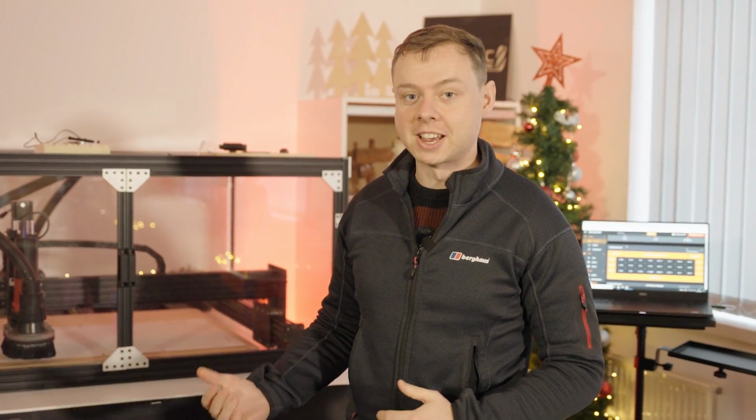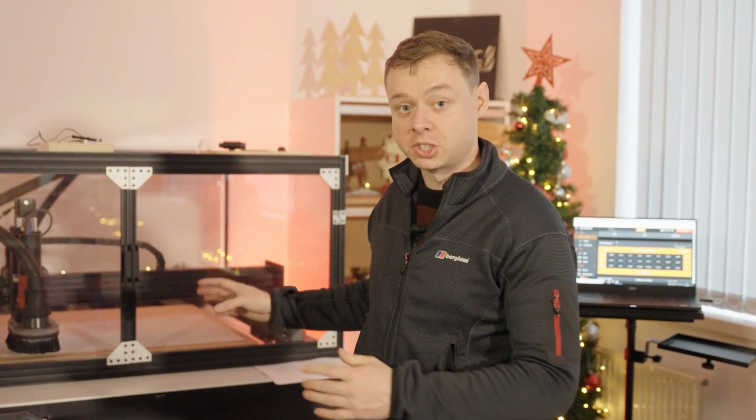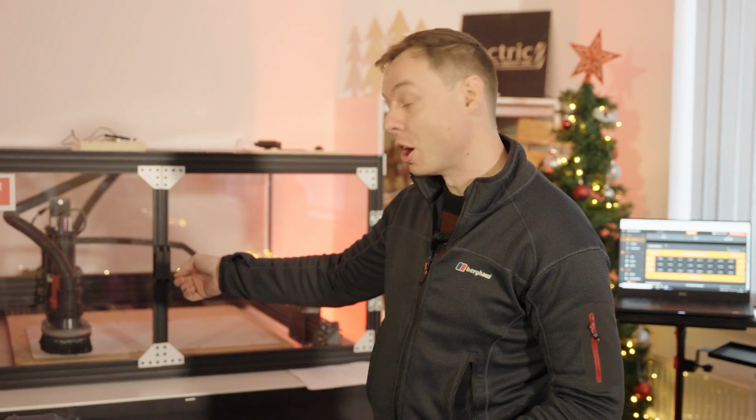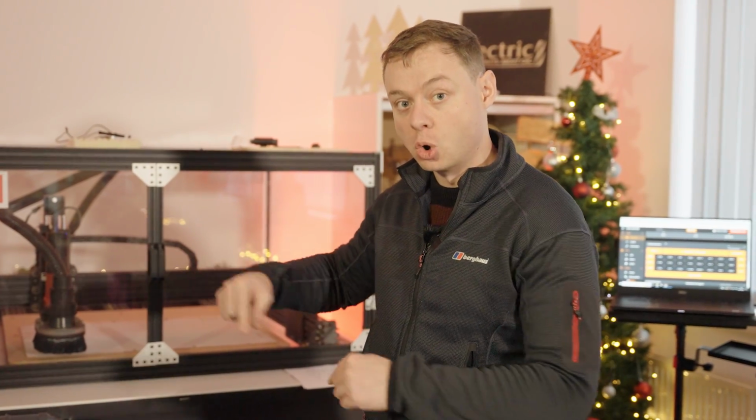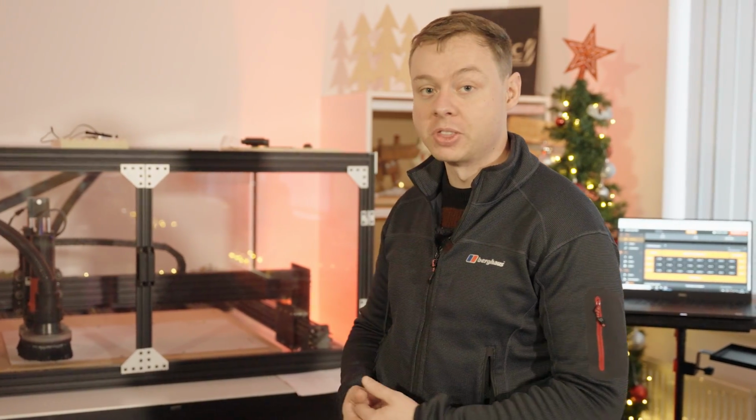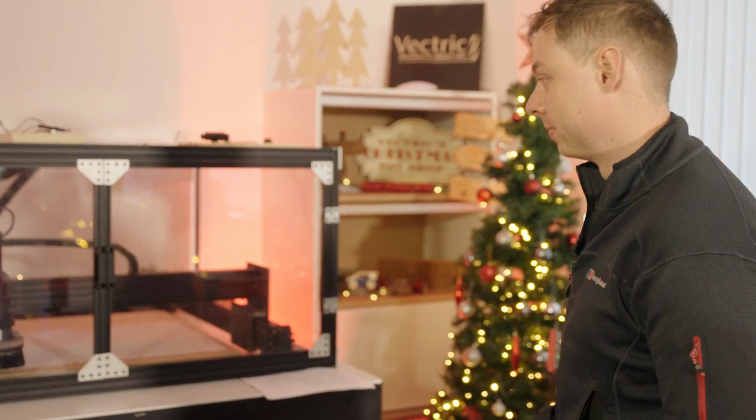Okay, so we've just finished the test cut, and I'm glad I did because we just needed to shift the material over slightly to account for the offset that I've added in, because I can actually screw it down on the very corner of the material. So now we've done that, we're happy with the positioning and feeds and speeds, so we're ready to get into the final cut.